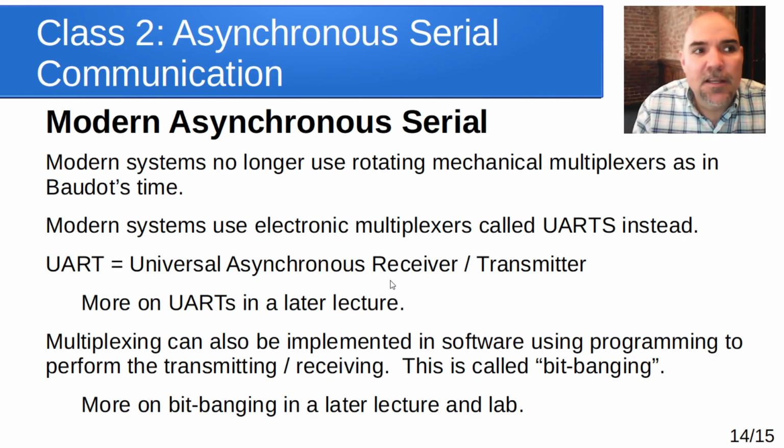And on the receiving end, it means you have code that's kind of waiting for the start bit. When it sees the start bit, it waits a while, pulls the data off the line or reads the I/O line, waits a little while, one bit width with a period, reads the next one, and so forth all the way to the end. So you can actually solve that both ways.